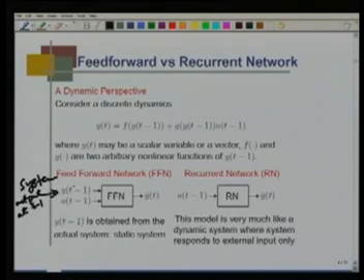So from the system I take the input, give to the network, from the system I take the output which is yt minus 1, and what is the input to the system, which is ut minus 1. Based on that I predict what is system output to be at t. So this is the predictive model using feed forward network for this type of dynamics.